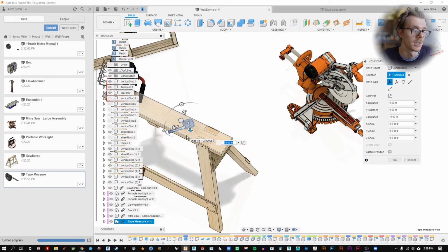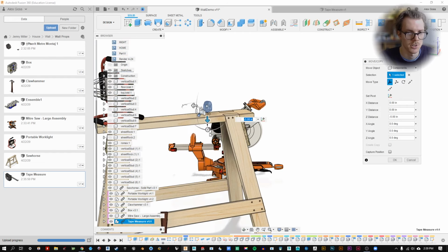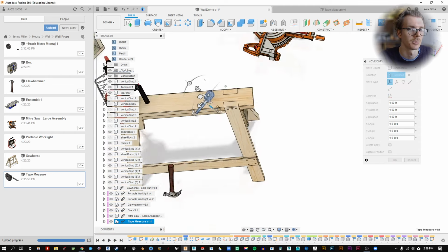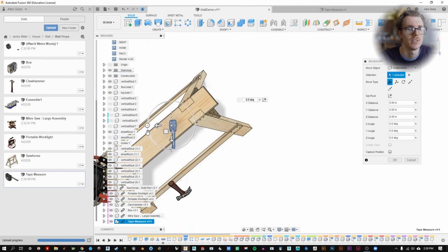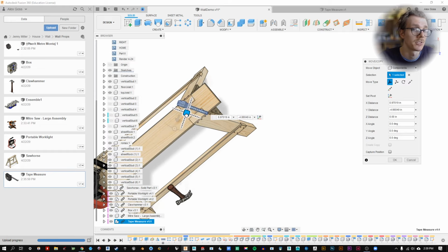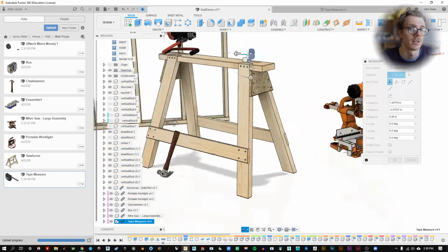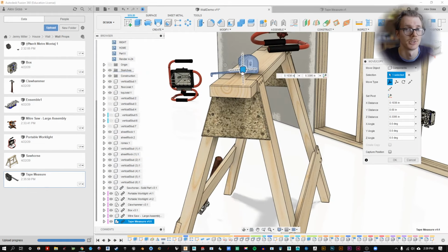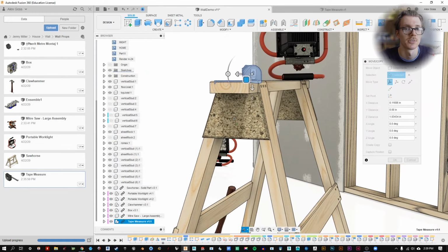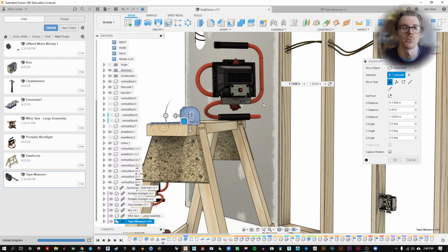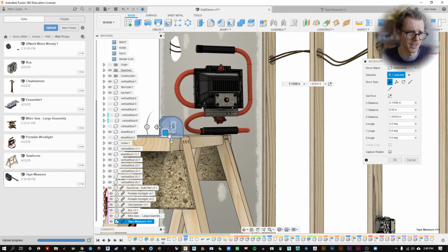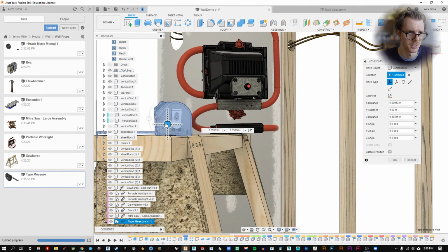So what I'm saying is sometimes when you get a mesh, like an STL or OBJ file, it's unclear if it was drawn in centimeters, millimeters, feet, fathoms. It could be so many things, and without knowing what the maker's intent was, sometimes it can be really frustrating when you bring a file in and you're trying to match it to other real world dimensions, and nothing really translates.